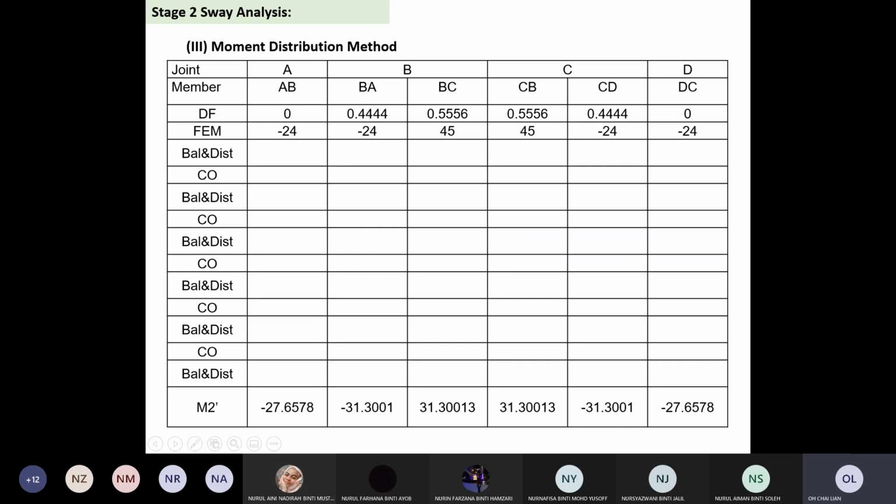Okay, how to get this R prime 53.04. If you notice, just now the R is 30 kilonewton positive, which is acting to the left, and now R prime is acting to the right, 53.04. So you need to make sure that this R and the R prime must be acting oppositely. If R is negative, the arrow is opposite.